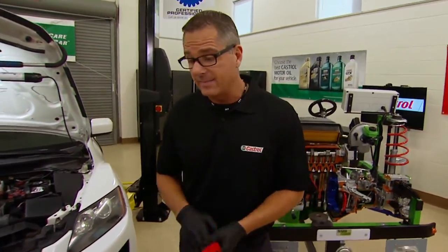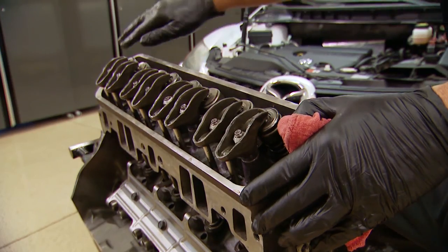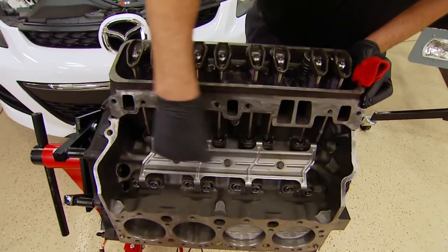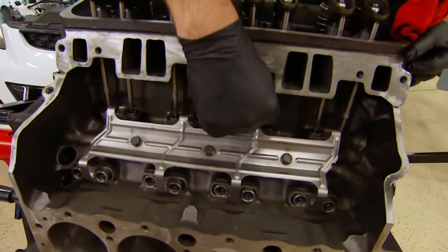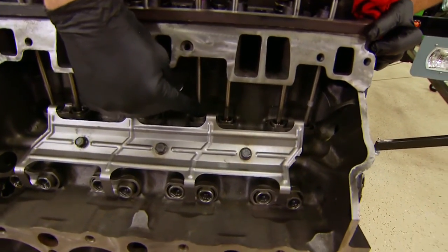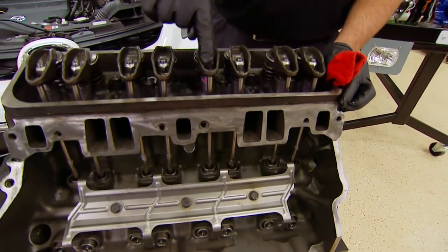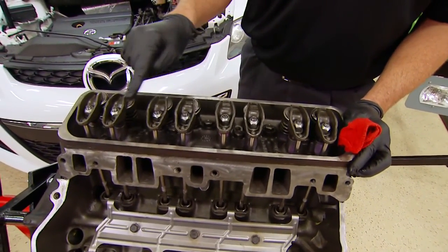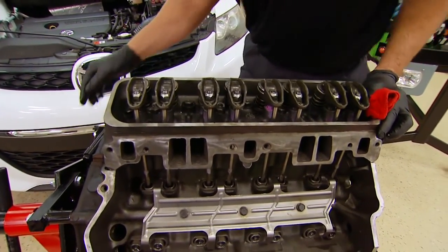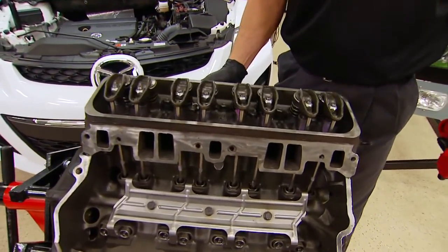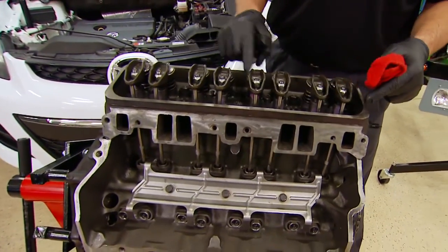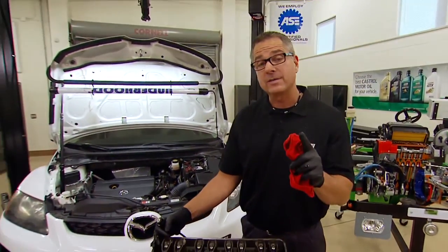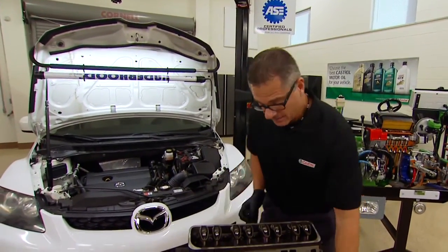Now, on an overhead valve engine, it's a little bit different, but it's the same concept. You can see right here, this is an overhead valve engine because the valves are up here and the cam's in the block. And what we're looking at here is the lifters. Each one of these lifters are filled up with oil, and then with oil pressure, they're going to pump up this push rod right here. And as they come up the push rod, they have to squirt out here and lubricate all these moving parts. Oil is very important. So if I spin it over, you can actually see each one of those rocker arms are moving, and oil has to happen. Now, oil also has to get back down to the bottom, so let's take a look at the bottom end here.